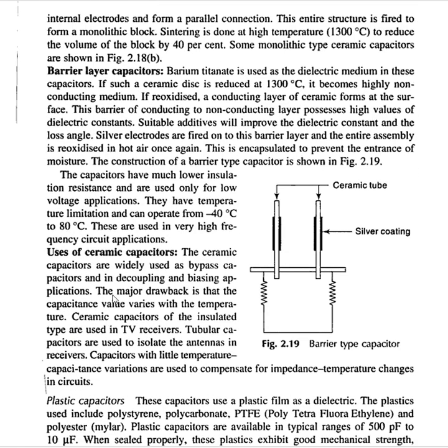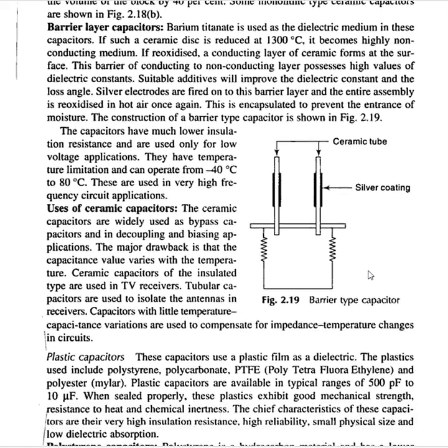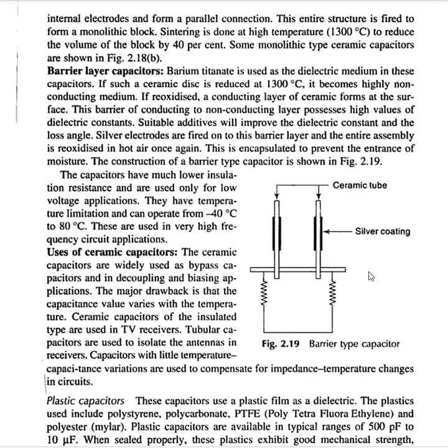Barrier layer capacitor, barium titanate. Barium titanate is used as the dielectric medium in these capacitors. If such a ceramic disc is reduced at 1300 degrees Celsius, it becomes a highly non-conducting medium. If reoxidized, a conducting layer of ceramic forms at the surface. This barrier of conducting to non-conducting layer possesses high values of dielectric constant.